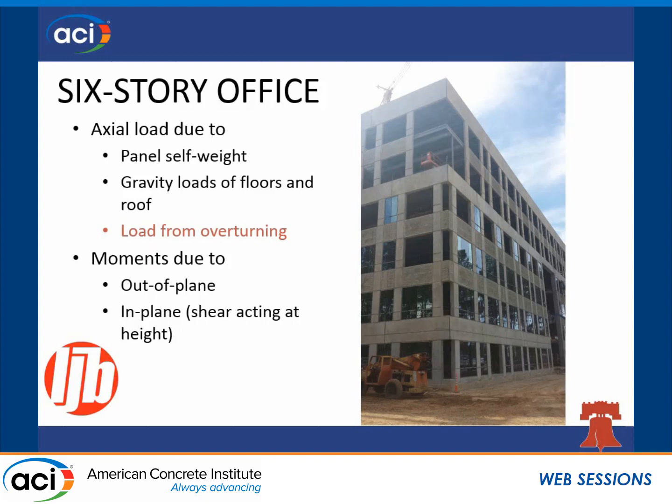Doug commented on this in his big box presentation about joining 2 panels or 3 panels together, and as that overturning comes in a multi-story design, especially one that has the panel with so much opening area in it, you do have an added axial load in those legs because of that overturning effect. Obviously, you've got the out-of-plane loads and the moments associated with that from wind or even in a high seismic area, that force acting perpendicular to the plane of the panel. But that overturning also creates in-plane moments between your beam sections and the panel that have to be considered.